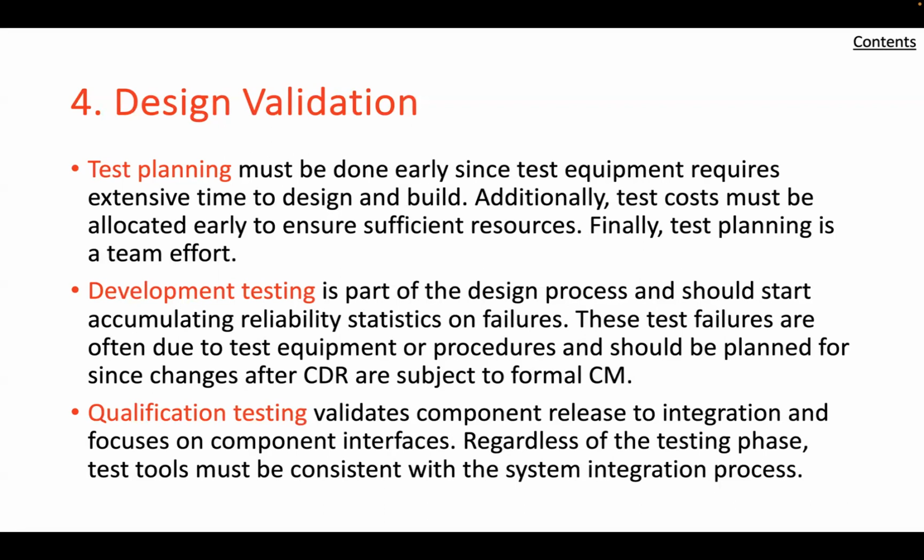The critical point, of course, is that each component interface must be designed to fit exactly with the connecting components and with the environment. So tolerance is another thing that needs to be thought about. The specification of component interfaces to ensure fit and interchangeability involves the assignment of tolerances to each dimension or other interface parameter.